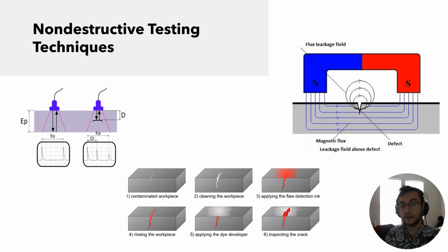Ultrasonic, as seen on the far left, the main principle is that you send an ultrasonic vibration through the material, and theoretically there is a signal you would receive if the container had no cracks. But if there was a crack in the way between the vibrator and the end of the piece, you would have a slightly different signal because the ultrasonic vibration doesn't travel nearly as far.